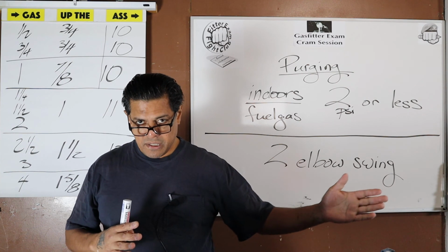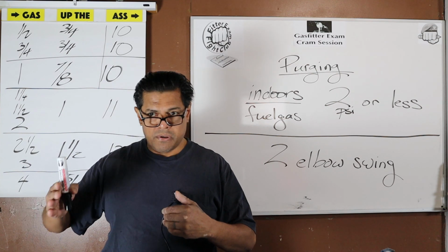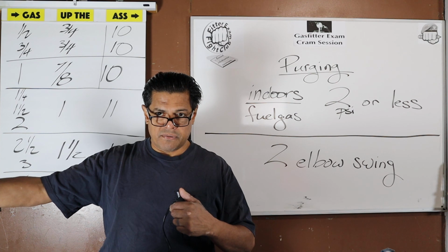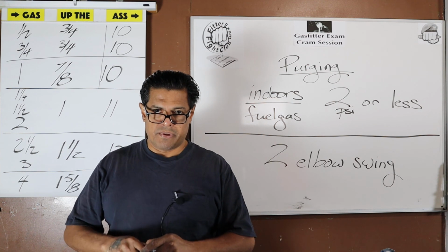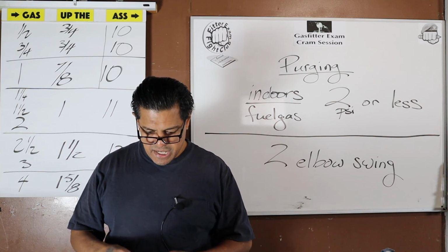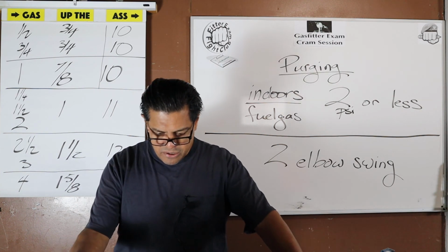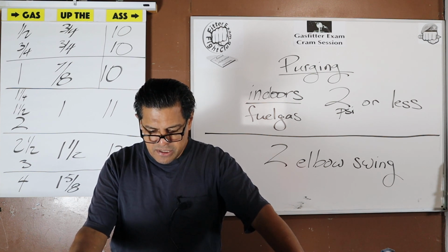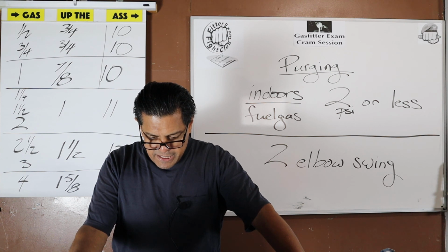From the main, in the street, underground, to the basement or cellar, it's going through the wall, it's finally going to stick out of the wall, house control valve within 2 feet of where it entered. That piping going through the wall, like any piping you would want to put through the wall, is got to have some kind of protection. In this case, we're going to encase it in a protective sleeve. Okay? So, gas piping entering through a foundation wall underground shall be protected by encasing it in a protective sleeve.